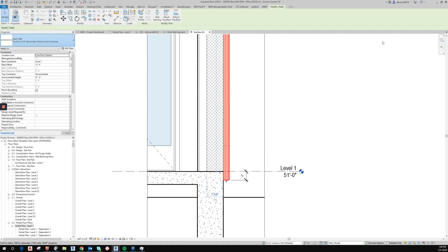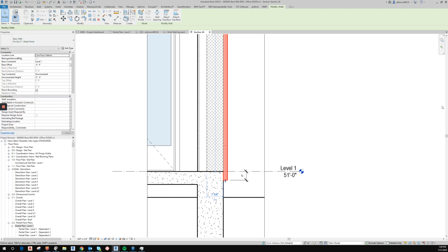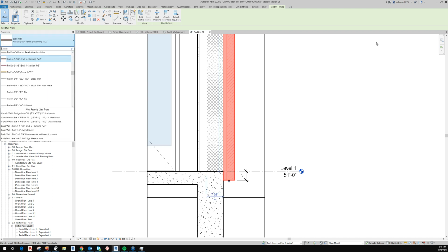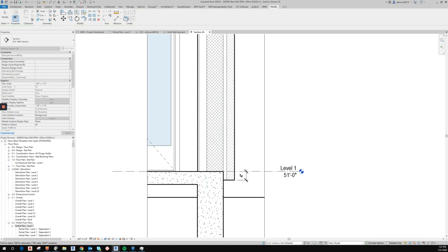And the reason you want it there is so if you need to swap it with other finishes, you can, and it grows. It doesn't move anywhere nasty. So if you had brick, you can swap it there. See what would happen if I switch that to finish face exterior, and then I were to swap it back to something, it would be away from the building. So that's why it's important to recognize where we put our location line. So we'll go back to that.